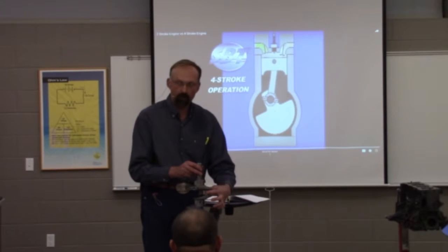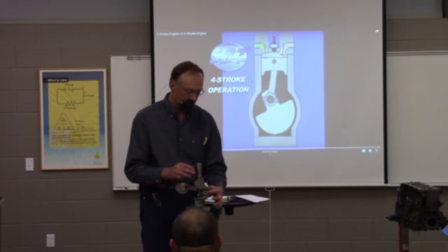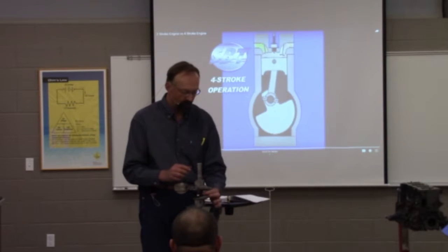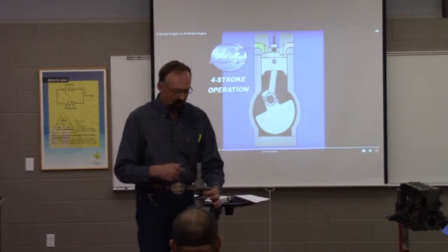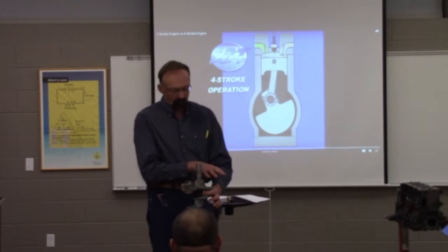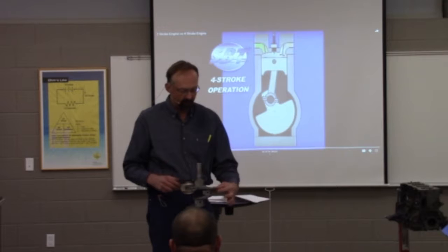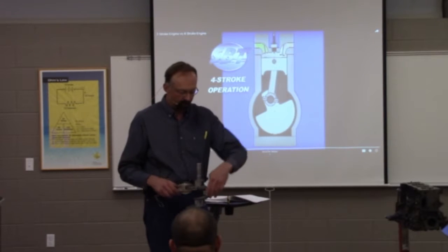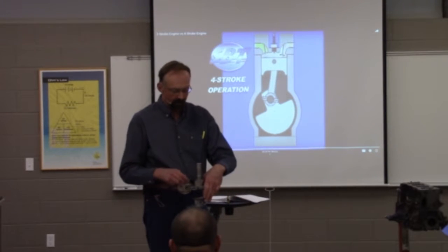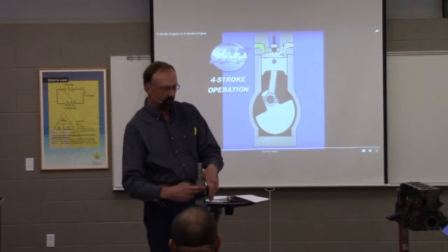Well, there's a portion of that mass that also moves with this throw of the crank. And they have some pretty sophisticated formulas that take into account part of the weight of that connecting rod and the weight of this part of the crankshaft, and they want to balance it using this.